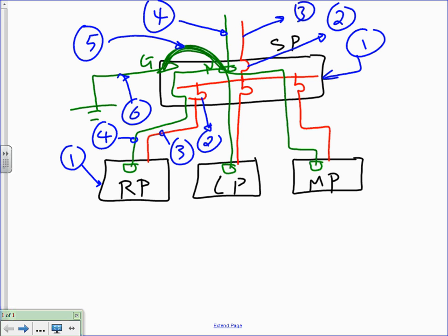Let me go get you the information that you need to size. So this is how the building is going to look. When you walk into any commercial building, the first thing you're going to size is the main panel. From that main panel, almost always you tie three more panels, for a big commercial building. The first one feeds all the receptacles, the second one feeds all the lights, and the third one feeds all the mechanical equipment. Does that make sense? Any comments, guys, about the given? So our job, my friends, your job and mine, is to size this system.